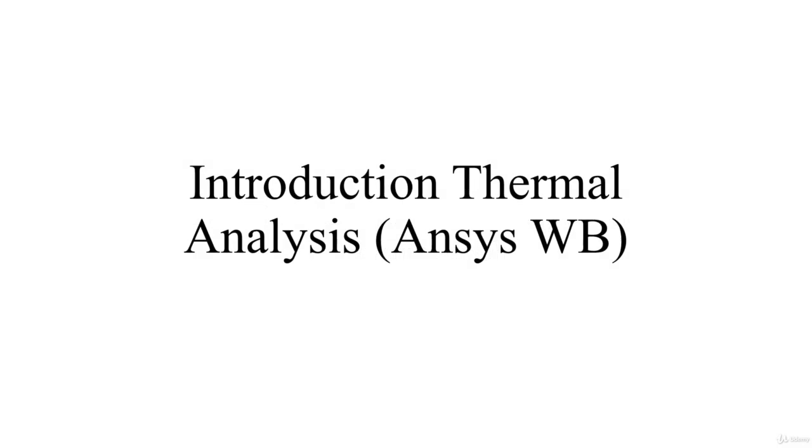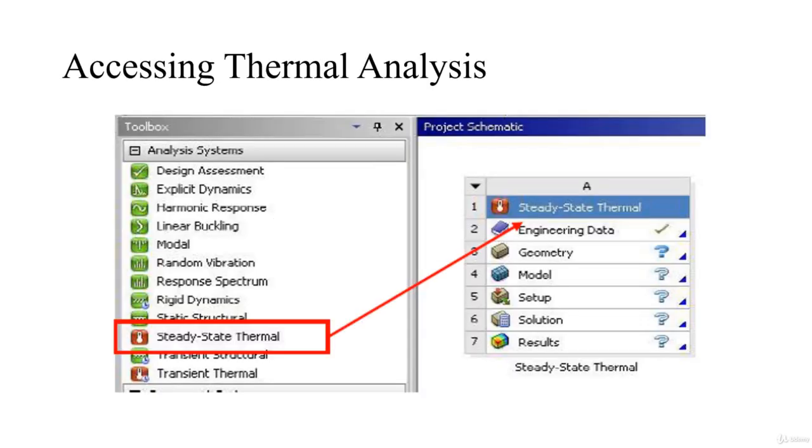Introduction to thermal analysis inside Ansys Workbench. In this lecture, I am going to tell you how you can access thermal analysis inside Ansys Workbench. So, accessing thermal analysis: you go to the analysis system, select the steady state thermal analysis, and drag it and place it on the project schematic.